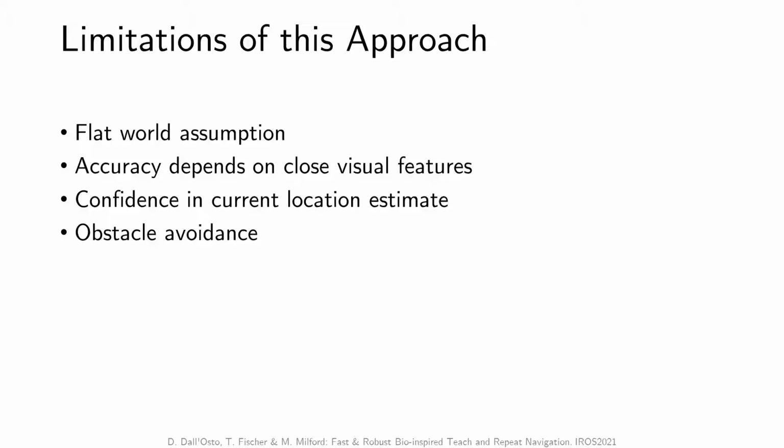Secondly, the system's accuracy is reduced if there are no nearby visual features. Faraway objects will not appear to move if the robot is laterally offset from the path. This limitation is typically acceptable if high accuracy is not required while the robot is traversing a large open space. If the space then starts to narrow, image offsets will increase and errors will be corrected more quickly.